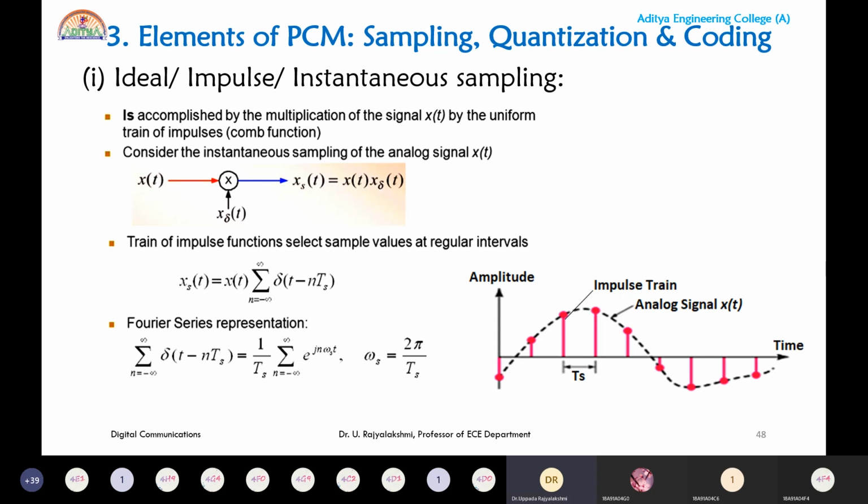You need to specify that it is a band limited message signal, because you used a low pass filter at the transmitter section, which eliminates the frequencies beyond fm. Okay, so the input message signal is an analog signal or continuous signal which is band limited to plus or minus fm. Its frequencies range from minus fm to plus fm, but not beyond plus or minus fm. So beyond the negative frequency minus fm and beyond plus fm, there is no signal component.